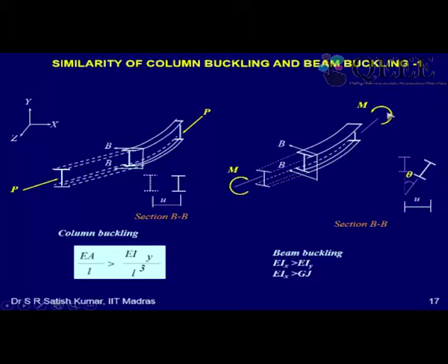So in beams also, same thing. For ideal beams, we derive the MCR based on the equal and opposite moments M applied. So here we note that we derive the equation for P critical based on equal and opposite forces and certain end conditions. Let's say if both the ends of the column are hinged, then P is given by pi square EI by (L by R) bracket square.